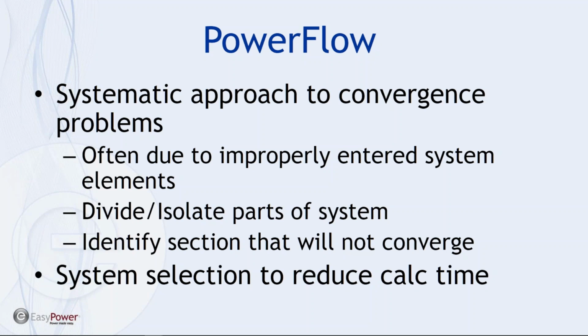Very frequently we'll take power readings, voltage and current readings when there are panel meters available, and then as we get the model developed, run a PowerFlow and see how close the results come to the actual parameters that have been logged, and that in and of itself will help identify system elements that were improperly set up.